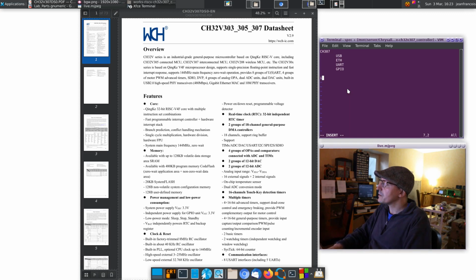We will need a crystal on board. I believe the board handles the 16 meg crystal as well as 32K for RTC, so we'll mount on board these two crystals. We also need a power supply. So we'll try to take from 7 to 30 volts DC supply. We'll include protection. Protections are defined as short circuit, over voltage, and reverse connection. To build the board, I will use KiCad 6.